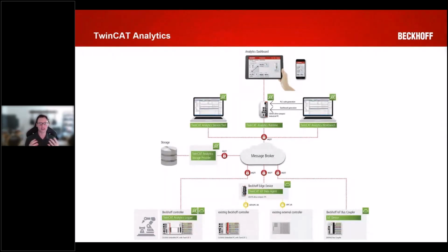So if you say, hey, log all these values, keep them for 7 days, and once you roll over the 24th hour of that 7 day, it just starts overwriting the oldest information. So you always have a 7 day window, the past 7 days worth of data, and it's a moving ring buffer. It has a fixed size, so it never goes beyond a certain size and crushes your disk. Great question.